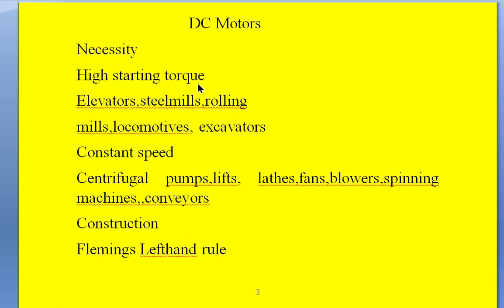Suppose we take elevators or steel mills, rolling mills, locomotives, excavators. All these devices use high starting torque. For this, we need what is called DC series motors.